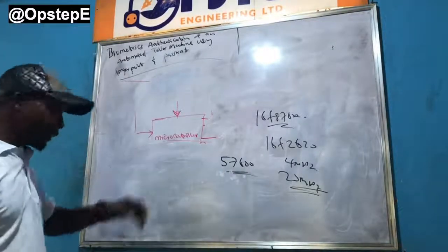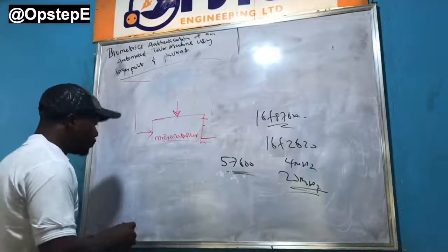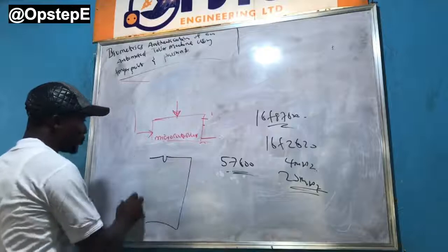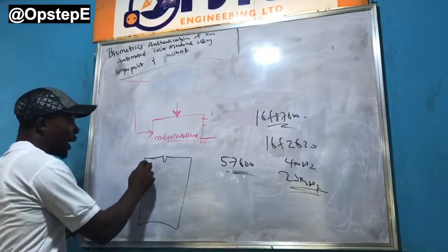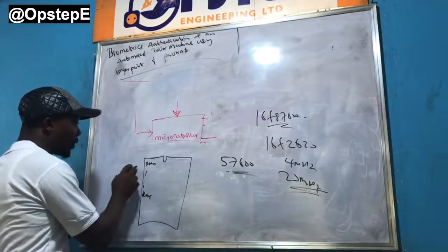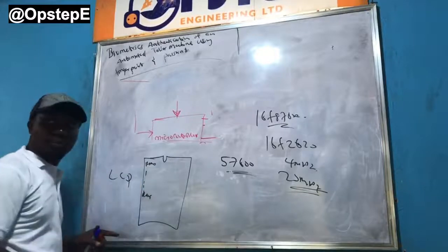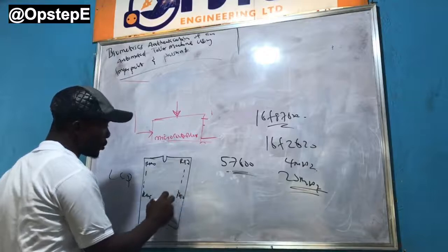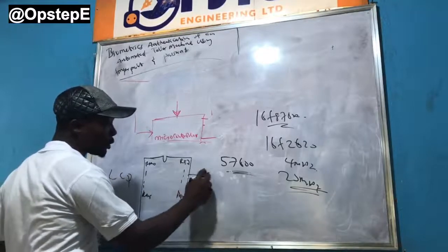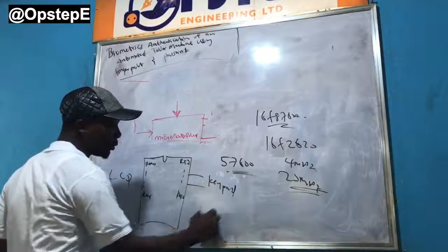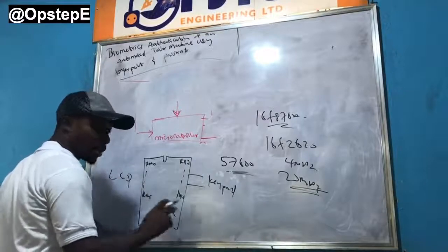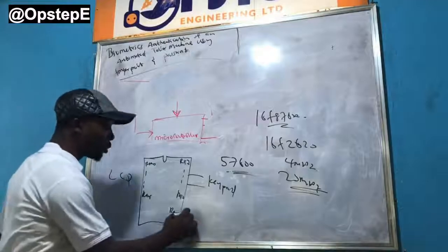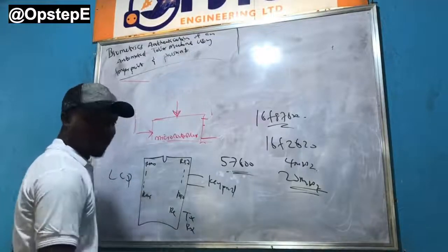So if you look at it from all that we've discussed, from your microcontroller, you know that your RA0 down to RA5 already has your what? Your SD. You know that your RB7 down to your RB0 already has your what? Your keypad. So your RC, I'm not sure the bits, would have your TX/RX.